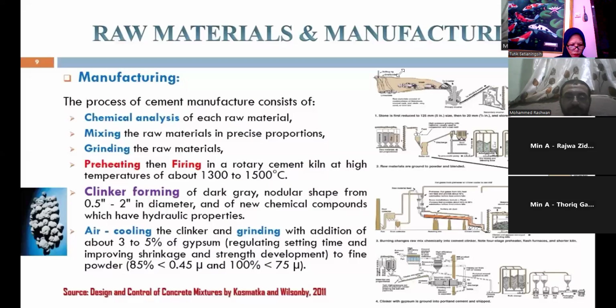The importance of the gypsum comes from regulating the setting time, because without gypsum, the produced clinker, when it reacts with water, sets completely without time.